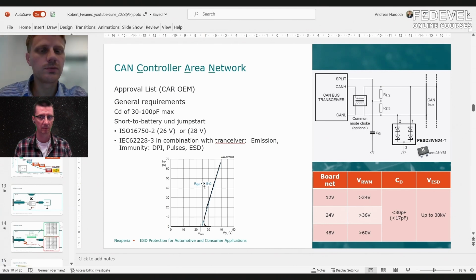I think for USB, the ESD protection devices that we have are from 3.3 volts to 5 volts roughly. So this is the region, a much lower voltage range. So not 24, this is much too high. For high-speed interfaces, and for USB, you usually go down to roughly 3 to 5 volts. In some applications even below 3.3 volts, because the voltage swing during data transmission is below 1 volt.